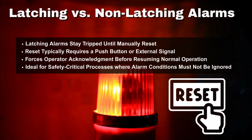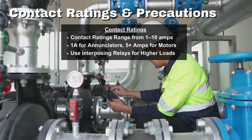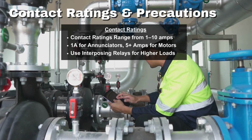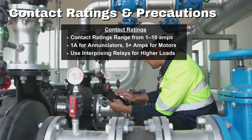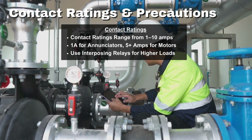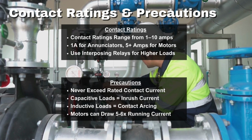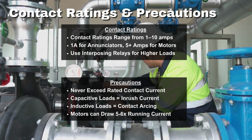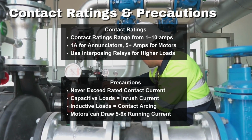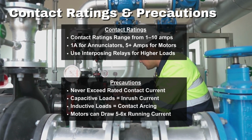Contact ratings of alarm trip relays typically range from 1 to 10 amps. A 1 amp relay is fine for something like an annunciator, but controlling a motor typically calls for 5 amps or more. For even higher loads, like pumps, you'll need to use an interposing relay. 2 precautions are critical. Never exceed the relay's rating, even briefly, and always consider the type of load. Capacitive and inductive loads can cause damage through inrush current or arcing, and motor loads can draw 5 to 6 times their normal running current at startup.